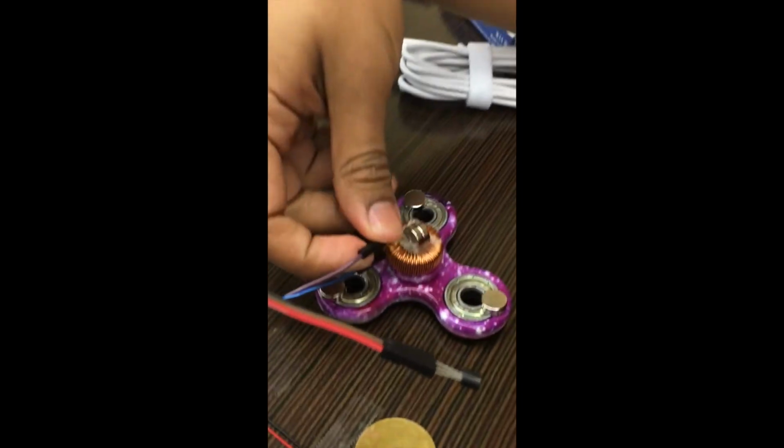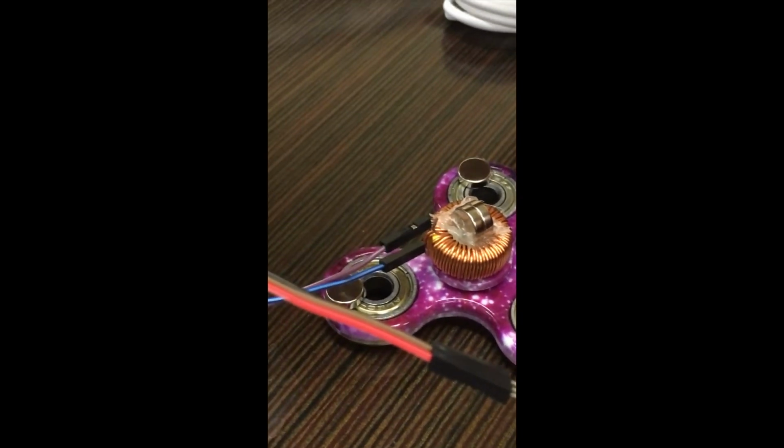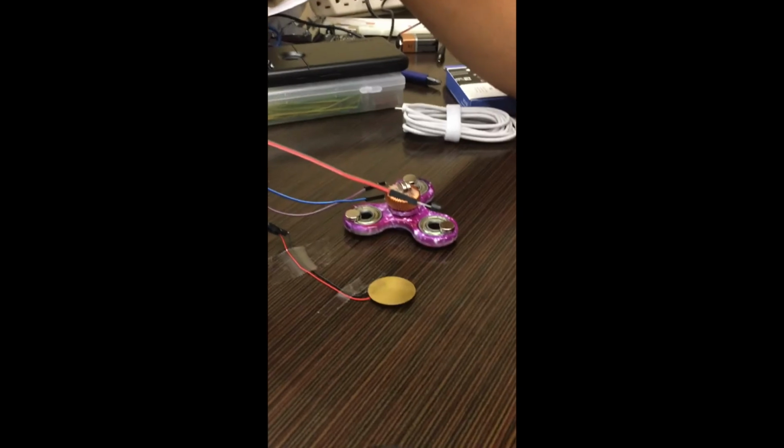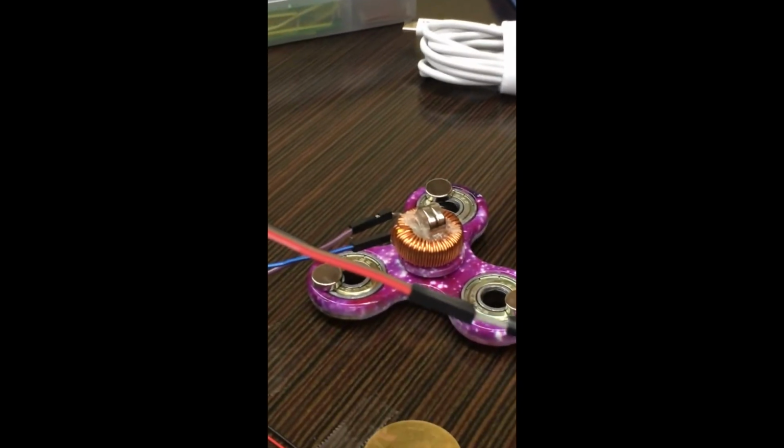So the way the circuit determines power generation is that across the inductor, when the power goes through, it's going to be read on an analog pin in the Arduino, and then that gets mapped accordingly. And it's a small range, but we're still able to notice it on the program, and we just print that out. It goes into our blockchain and we can verify it.